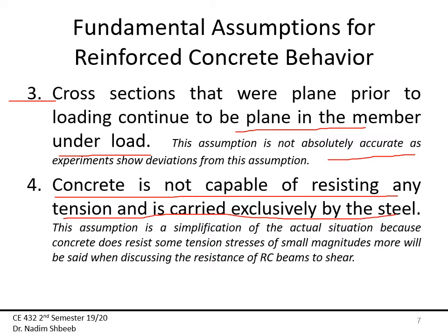Pretty much what I'm saying here is that I will assume that there is zero stress in concrete. It does not exist for me in tension. Although we know it is there, and there are some small magnitudes, again, I will consider them to be non-existent.